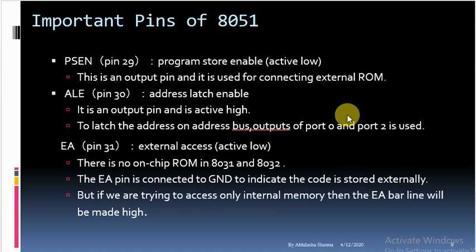Yes, till now we have discussed 32 pins of the 8051. The next important pins of the 8051 that we have to discuss, the first one is PSEN. PSEN basically implies program store enable. This is an active low pin, which means it is read out as PSEN bar. So it is activated when a low signal is applied here.